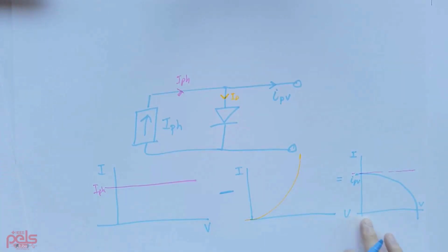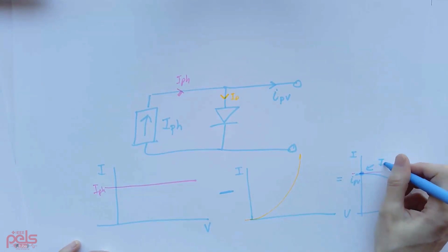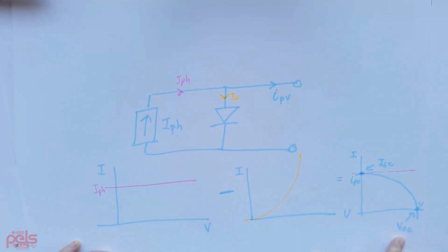And we'll notice this is a non-linear characteristic, and that it will not necessarily create power at all of the points. If it has zero current here, for example, at this point, this is called the open circuit voltage, VOC, or it's operating here. This is the short circuit current, I short circuit. There's going to be no power. And if we do the calculation for this, we'll see there's one maximum, we call this the maximum power point, that is right near the knee of the curve.